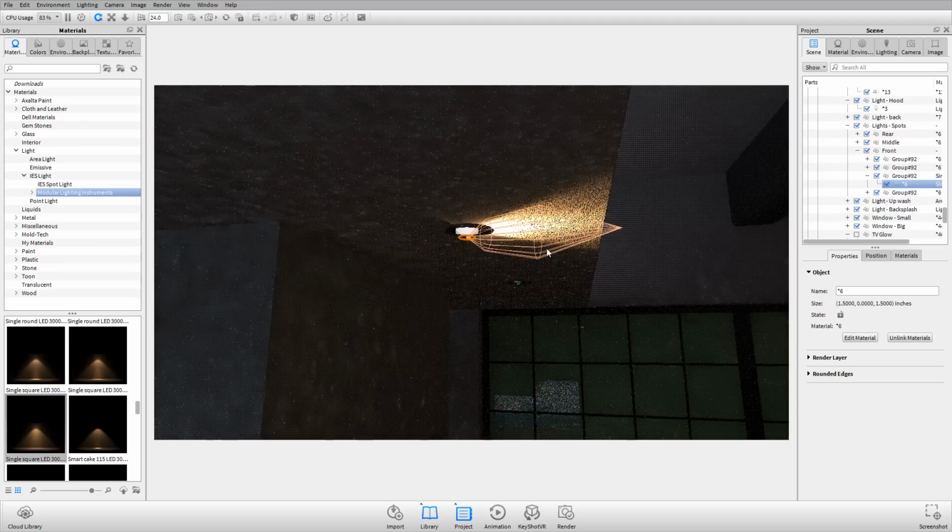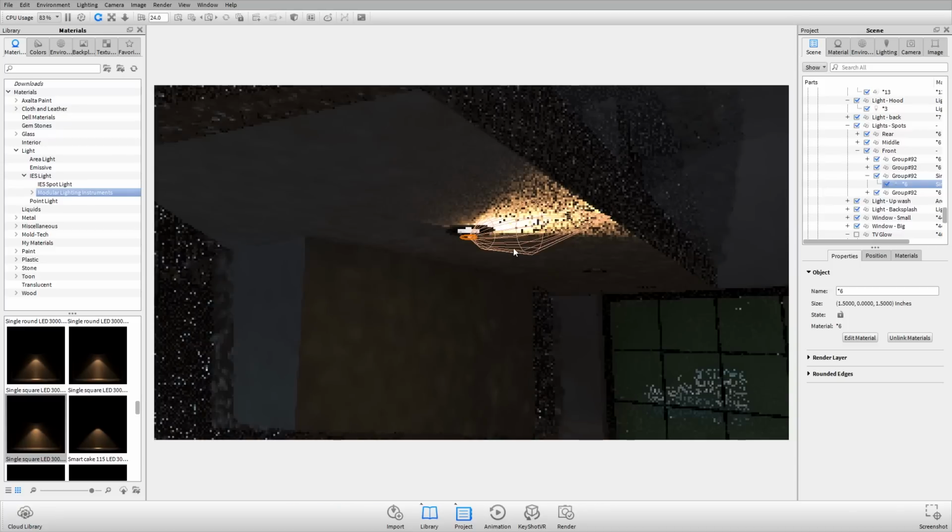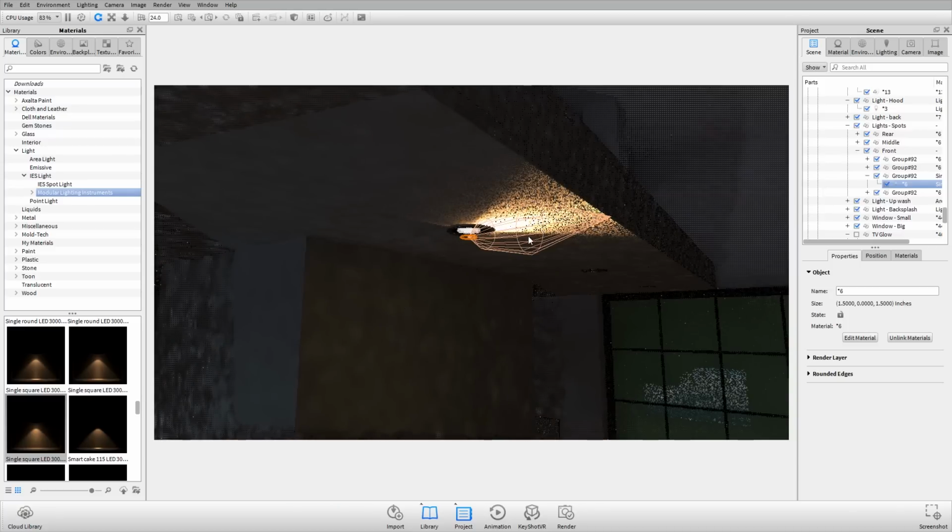Right now I'm getting this directional light in my scene, which is awesome. It is definitely pointing in the wrong direction though. And this is where IES profiles are something to consider. You need to keep in mind that since there's a direction built in, an IES profile may not necessarily match your modeling software or your intended origin. KeyShot is Y up, so if this wasn't actually created with Y up, then it's pointing out in some other direction. So I'll throw it in performance mode. Again, just speeds that up a little bit.